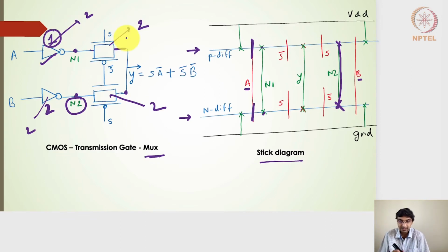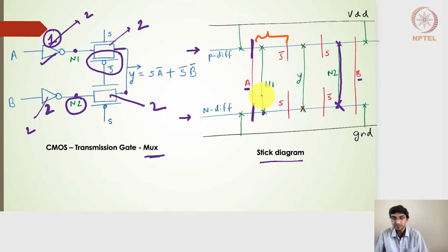of the transmission gate design multiplexers, you can see that the transistors A here on the P diffusion side and on the S bar, so I'm talking about this particular transistor, and then the inverters' PMOS transistors. So this particular line, let me draw this, is a merged diffusion because there are 2 transistors and the diffusions are merged. Even though the diffusions are merged, there is a contact here. So the metal line is going around. That's why it is called metal contacted merged diffusions.